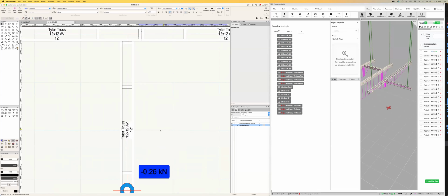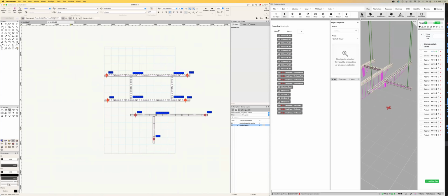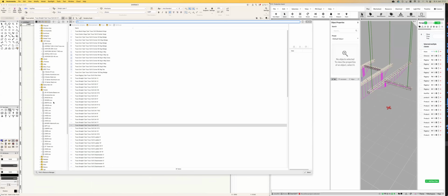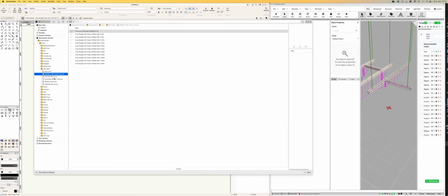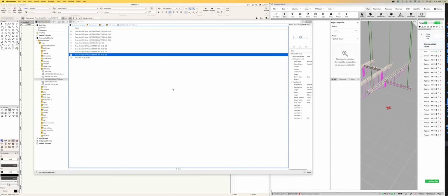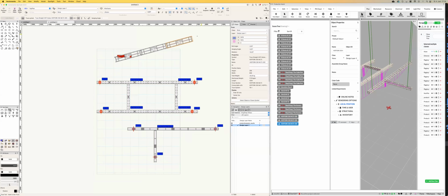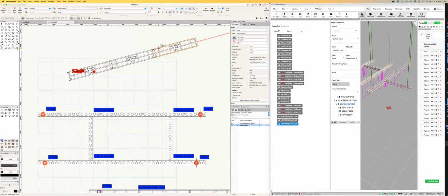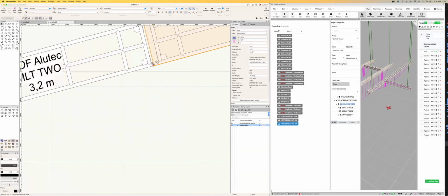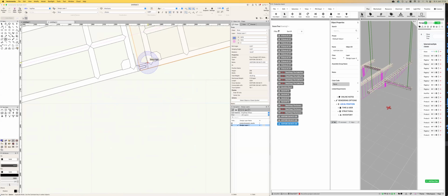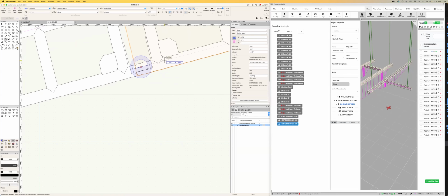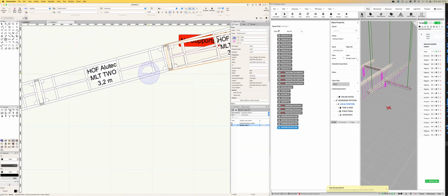That's right. Okay, thanks. The next thing that we're going to do is have a look at the MLT truss. A typical problem that you have from time to time is that you want to curve something in here. It's sometimes a little bit challenging to curve these things. So when you're doing this, you can go in here on the connection part, and then you can curve it by the degree that you have in here.